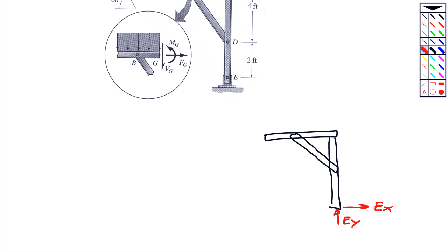There's going to be a roller force acting at A, which I'll call just a normal force NA. And then there's going to be a resultant force F from the uniform line load of W0. It's going to be at a distance of H to the right of there.